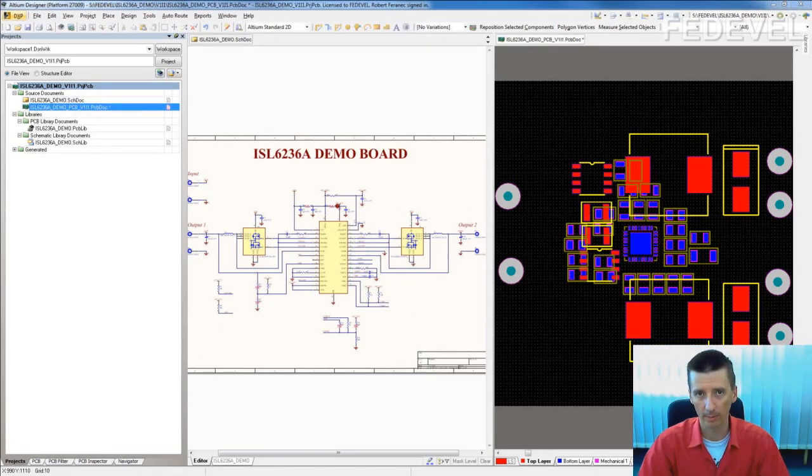To make it more comfortable to work with your PCB, we will create layer sets. Layer set is a kind of view where you enable just some layers which you would like to see. For example, for top layer, we would like to see only the layer where is the copper and the layer where is the outline around the components. So when you look on your PCB, basically the white color around the components. Here in our PCB, it is this yellow, and the copper is the red one.